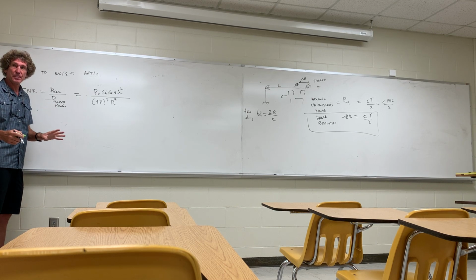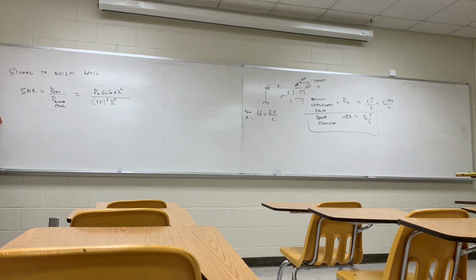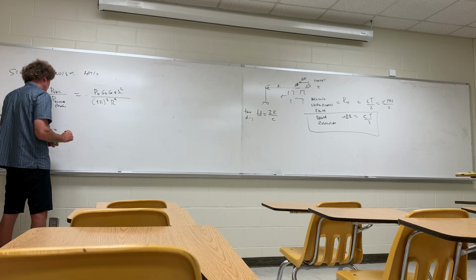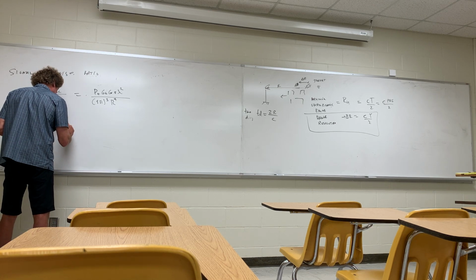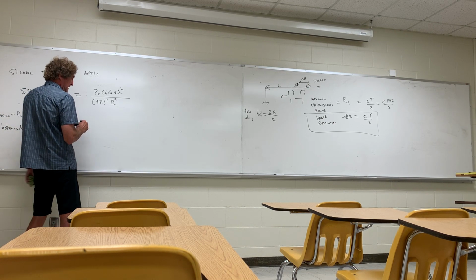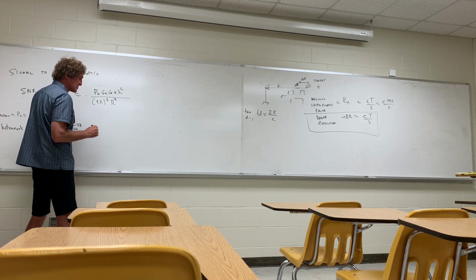We're doing monostatic here. Now, noise power, P noise, is usually just P sub n. That's k T times F times B. All right, k is called Boltzmann's constant. And k is 1.38 times 10 to the minus 23rd. And let's see, okay, let's use.